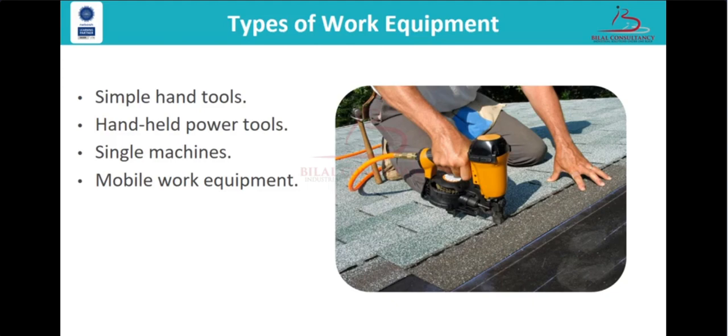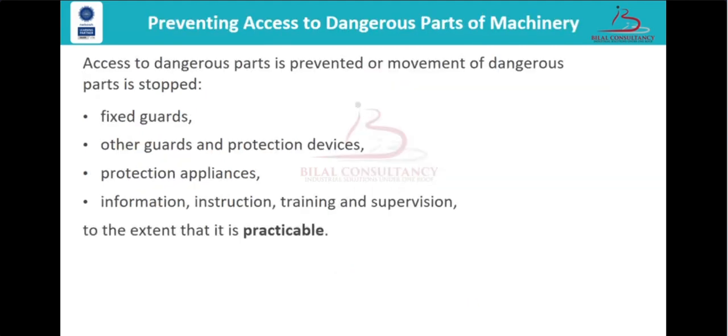Employers in Europe have to ensure that any equipment they purchase for work use has the CE mark and written declaration. Moving forward to preventing access to dangerous parts of machinery. Access to dangerous parts of machinery should be prevented. The safeguards that are used to prevent access to dangerous machine parts should be applied according to a hierarchy of control measures. The hierarchy of control measures is best understood by looking at a specific hierarchy created by the UK regulations,